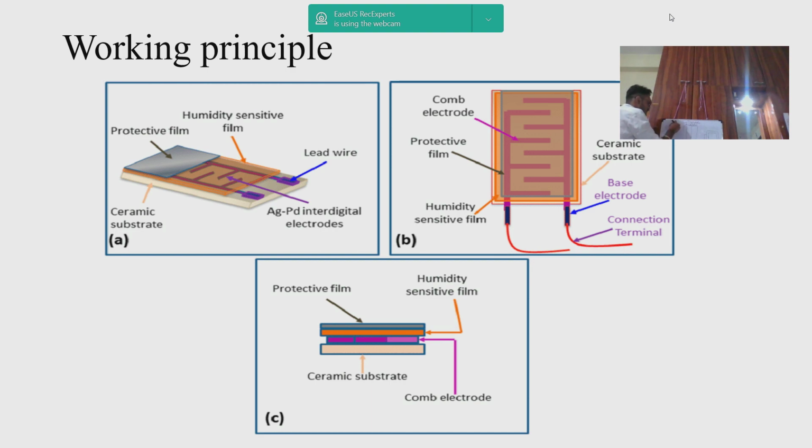When there is moisture around these plates, and the plates are produced with an electric charge, now when the moisture enters between these two plates, there will be some change in charge, and this charge is used to calculate the humidity on the monitor, which is kept for measuring it. This is how the capacitive humidity sensor looks.